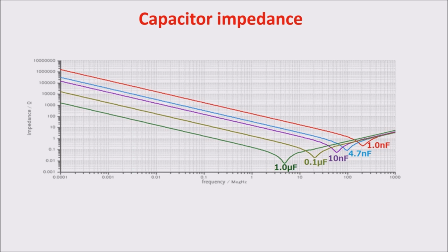You can see as the frequency increases, the impedance decreases, so less resistance to the flow of the current. So at very high frequency, capacitors behave like a shortcut, like wires. On the contrary, at very low frequency, capacitors show very high impedance, and they behave like an open circuit. You can see at the same frequency, small capacitors show higher impedance, so more voltage drops on them, so they can follow input signals better. Beyond a certain frequency, the impedance starts to rise. This is because in a real capacitor, permittivity becomes frequency dependent beyond a certain frequency.